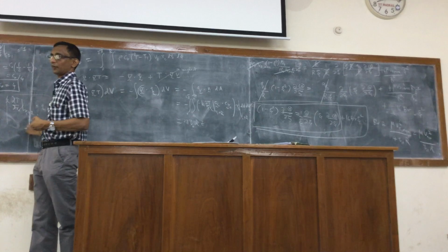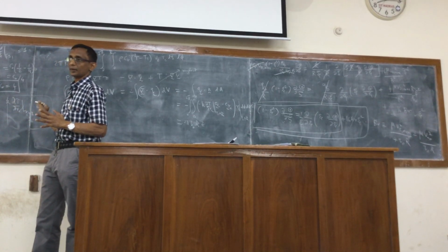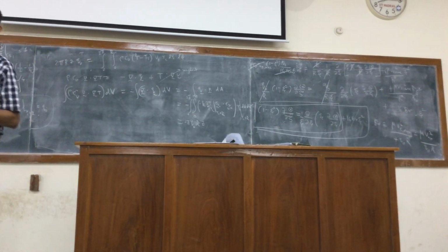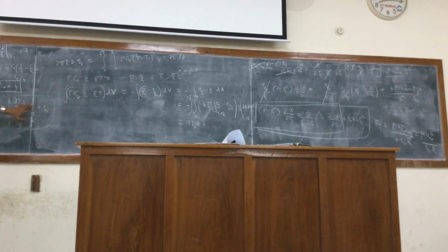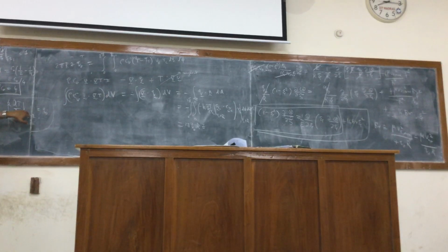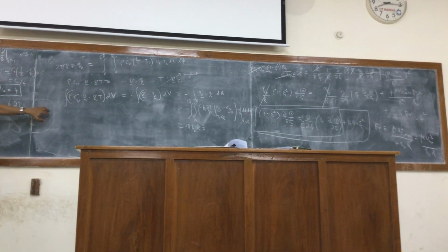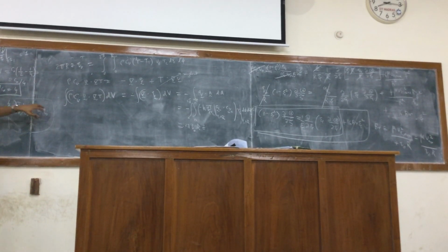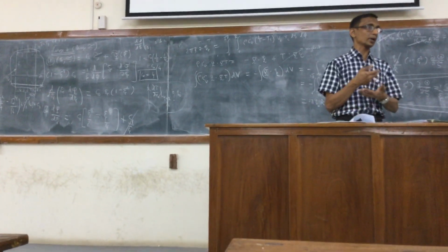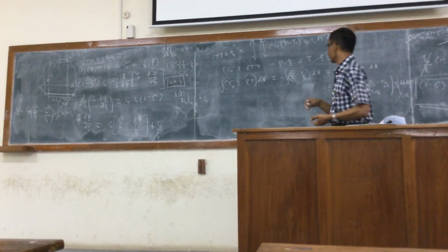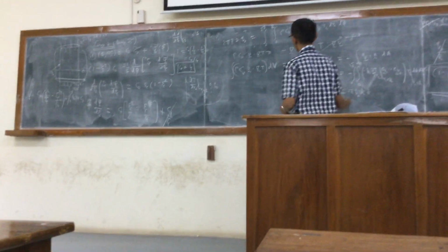You can easily verify the logic behind this. So once you have accepted this, then the formula remains as it is. Whether the fluid is being heated or cooled, when the fluid is heated, you would put Q naught greater than 0, otherwise less than 0. So that is what I have.